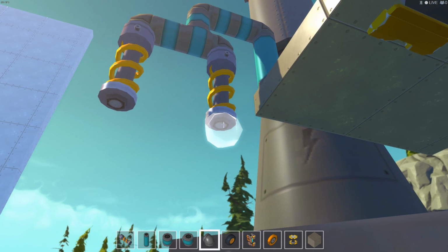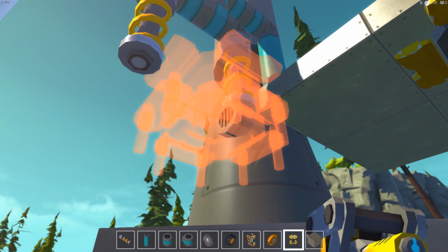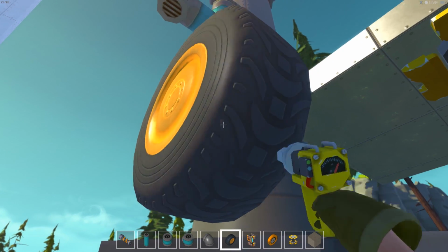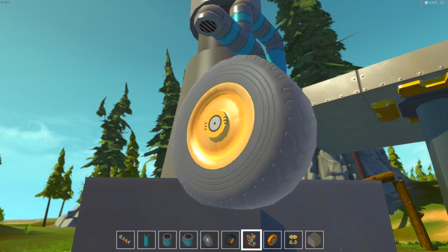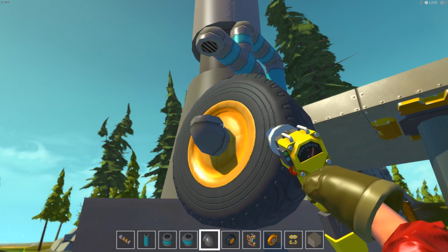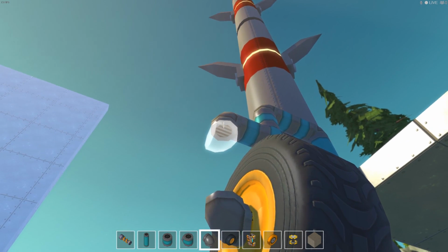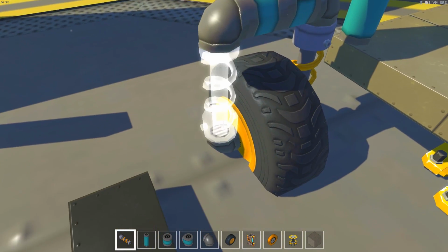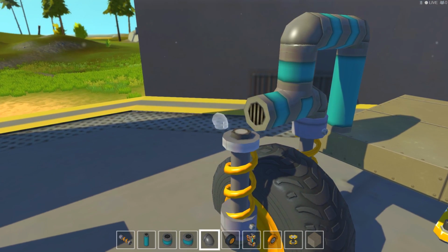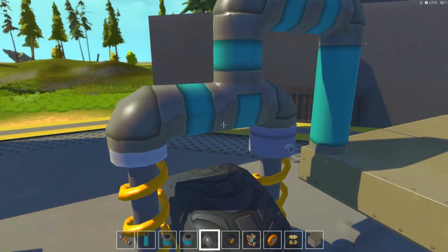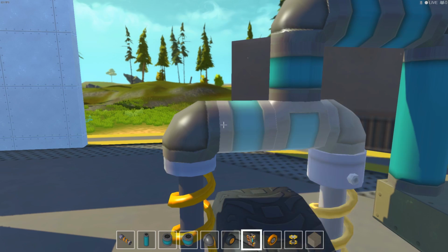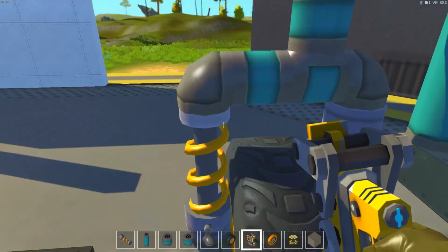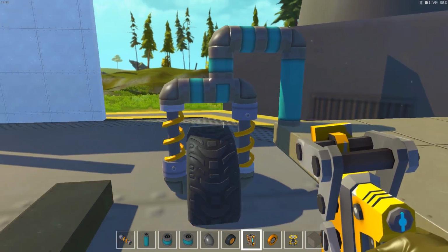All right, so what I'm gonna do, I'm gonna start off kind of normal here. Gonna add a bearing and a tire, a bearing, and one of these. And now instead of going down with the suspension, I'm actually going to go up with the suspension, because now I can add this elbow joint, and here's my weld point here. So you can see that this weld point has nothing to do with the bearing, so it's not going to affect the bearings. So that's one way.